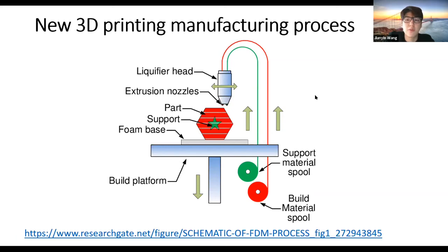One of the possible methods to improve the strength of FFF parts is adding reinforcing material, such as carbon fibers, into pure thermoplastic matrix material to form a carbon fiber reinforced thermoplastic composite.